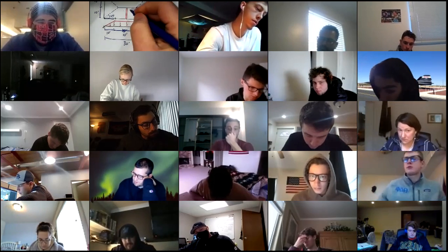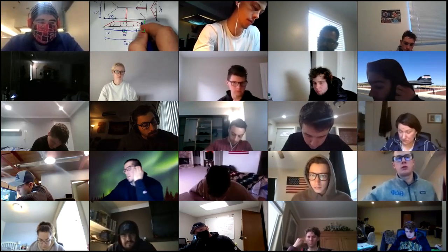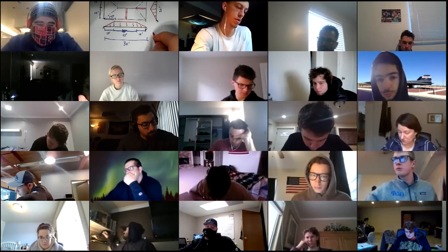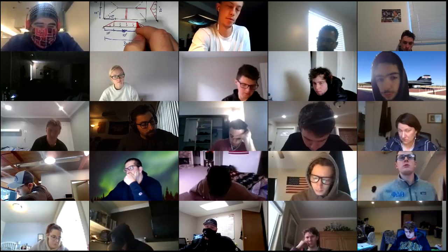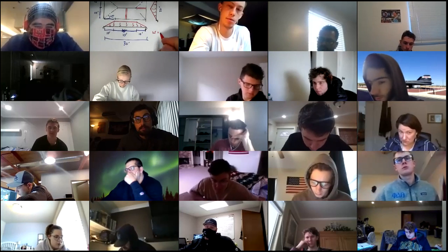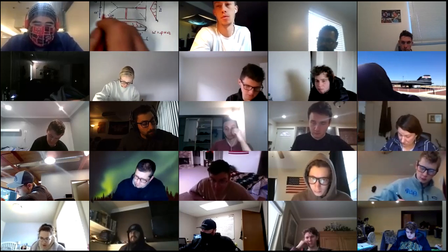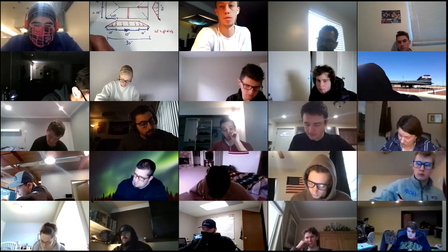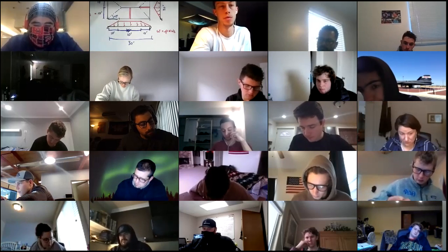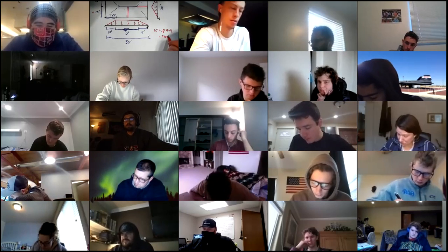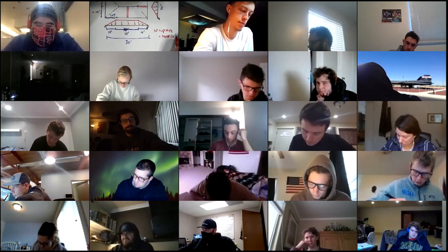And then this tributary load magnitude, the load magnitude W, that peak W here, is just going to be equal to our pressure times our tributary width. Our tributary width is that 10 foot right there. And so that's our 20 PSF times our 10 foot.